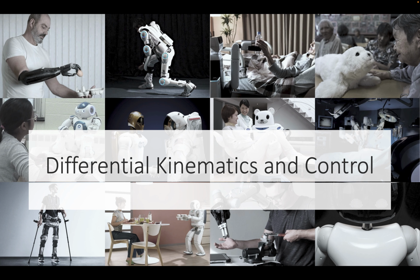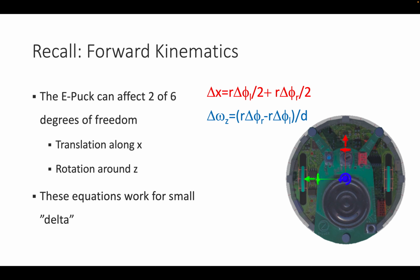Now we introduce the topic of today's lecture, which is differential kinematics and control. For this, we have to go back a little bit and recall how the forward kinematics of the mobile robot were computed. We came up with this idea to say you can't really tell where the robot is by just looking at the position of its wheels, but when looking at a small increment, which we use the symbol delta for, a small increment of the left wheel or a small increment of the right wheel, we can compute a small increment of forward translation.